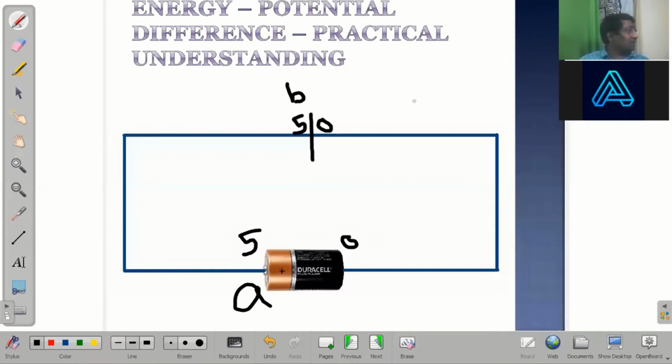The reason is, even if you try to touch a switch, right now, I'm touching this 9-volt part and my feet are not touching the ground. I'm not touching the ground at any point. Right now, electron movement will not be there in my body because the circuit is not closed. This positive is at 9 volts and my entire body is also at 9 volts. Since it's all 9 volts, there is no difference in potential. Electrons will not move and I will never get any shock. Even if I touch it, don't do this. This is just for theoretical sake.